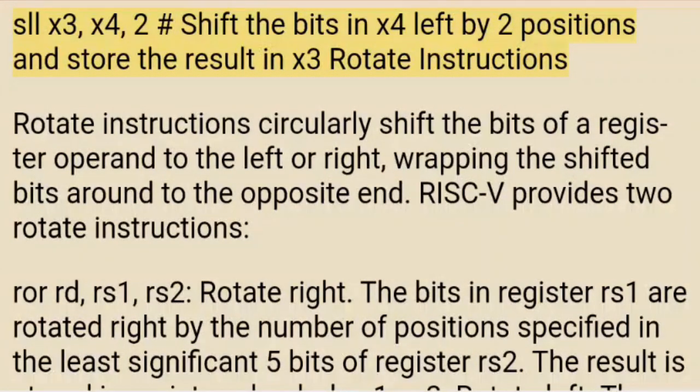Rotate instructions. Rotate instructions circularly shift the bits of a register operand to the left or right, wrapping the shifted bits around to the opposite end. RISC-V provides 2 rotate instructions.